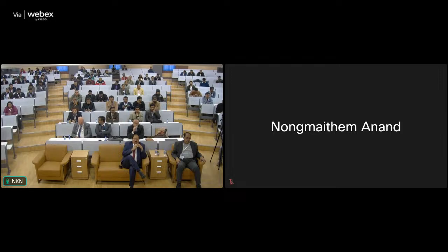And you will see that if you have uncontrolled blasting, then even in rock with Q equal to 40, you may have a large effect of full column rock bolt grouting. So I want to emphasize here that we should always treat or handle the rock with care. The reduction in support pressure shall reduce the shotcrete requirement and therefore the supporting cost and time. Thank you very much for listening.